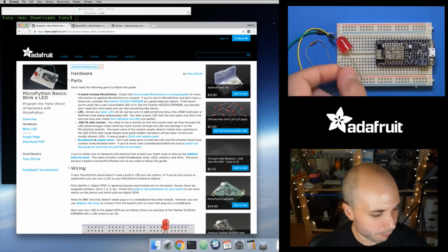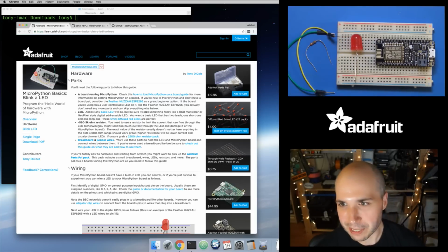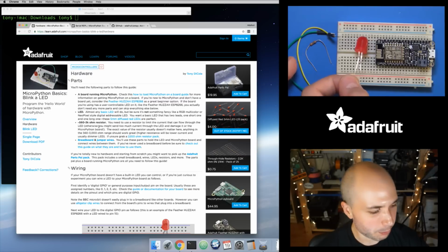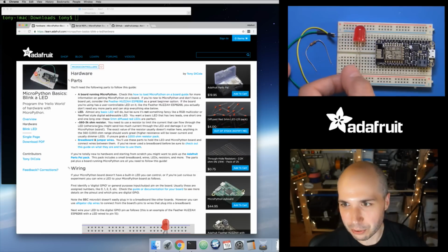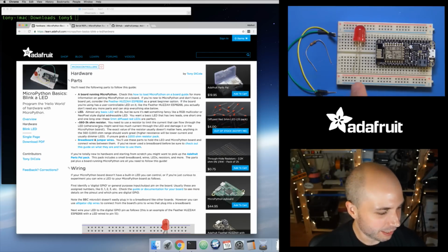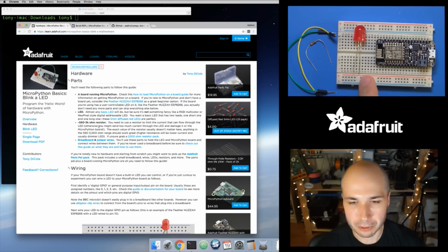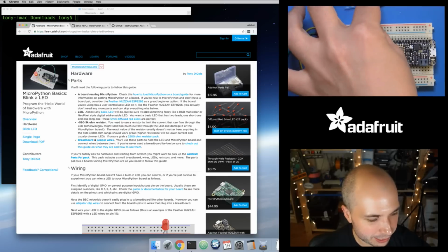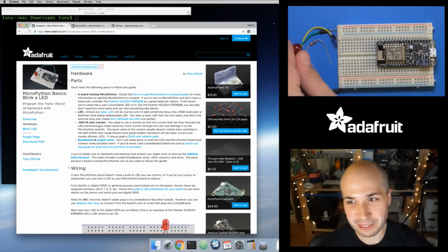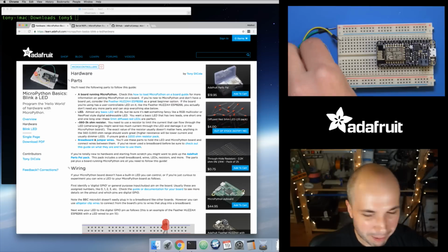Don't get a fancy LED like an RGB LED or a NeoPixel style, digitally addressable one. You want one like this that has just two leads. There's a positive and a negative, or a cathode and anode, connected to it. One lead is a little bit longer. Any kind of LED like this works, hopefully one that's in the visible light spectrum so you can see it. But you could use an infrared LED if you wanted. Maybe you have infrared vision.